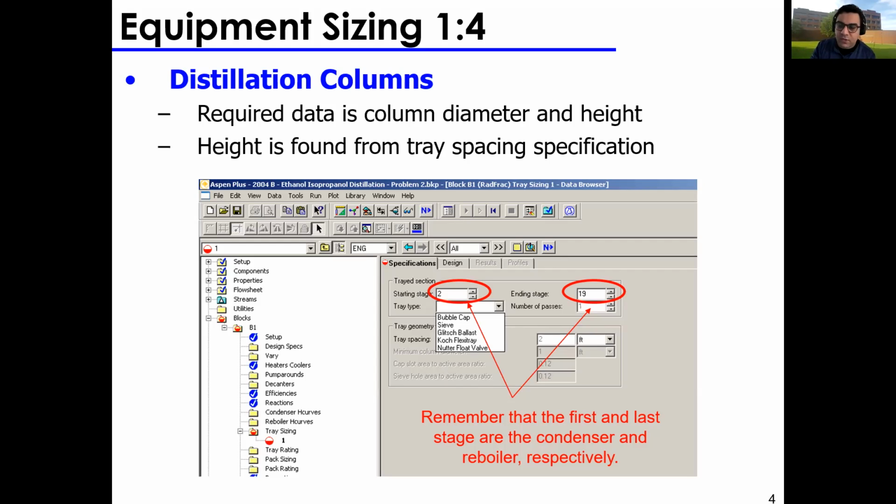You want to be very conservative, or you want to be very wild with your estimates and take major risks. It's up to you, but you have to take the responsibility for the numbers you present. So usually try to be conservative with all your estimates, efficiency 0.7, 0.6, just over-design it initially, and then you can zone in as you iterate, during your detailed design stage. You can always iterate these types of calculations.